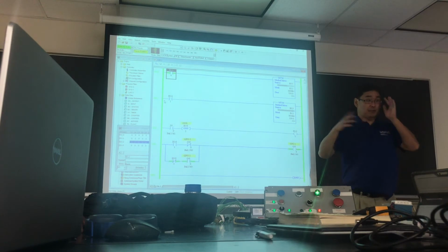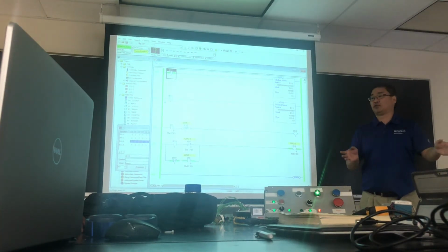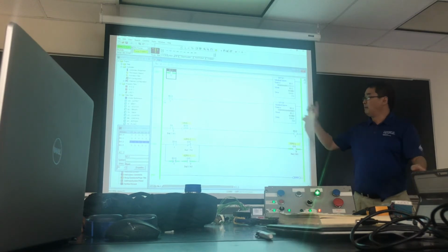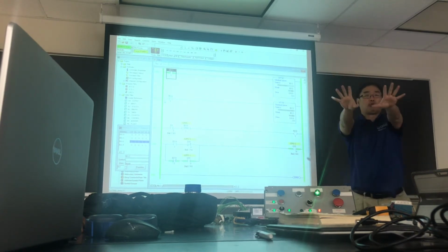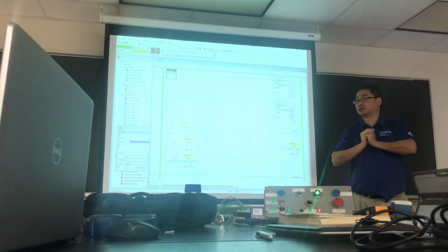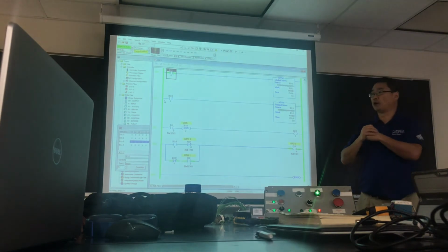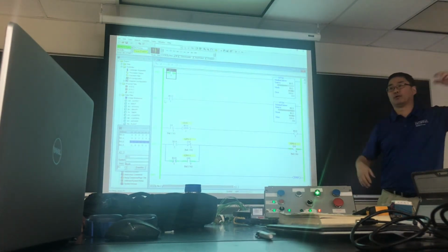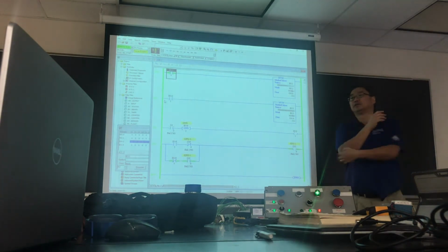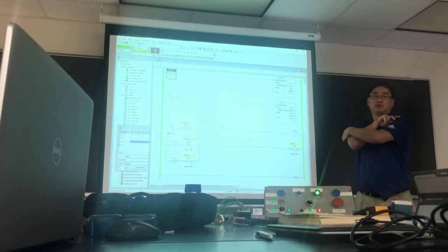So if I have a bunch of outputs and I know I need to preset a bunch of outputs for an operation, a mask move is an easy way to come in and say, okay, write all the settings at once, done, but only turn on and off the ones I want. The other ones might be a light stack or a warning horn or who knows what, and we don't necessarily want to turn those on. Does that help make a little more sense from this morning's discussion?